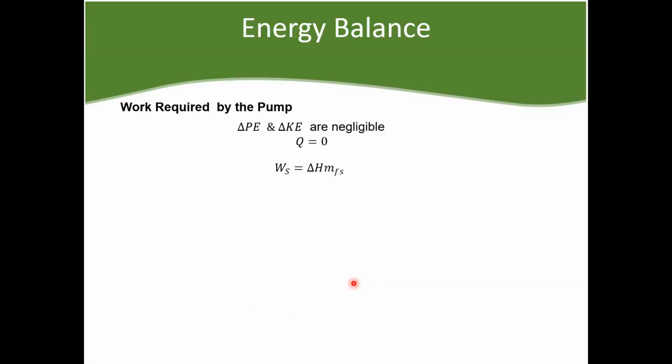How about for the pump? So it's almost the same with the turbine. We make the same assumption about the potential and kinetic energies, and we assume an adiabatic process. We're left with the same equation as the turbine. However, the properties of compressed liquids are seldom available, meaning the properties of enthalpy for compressed liquids are not as available as the steam properties.